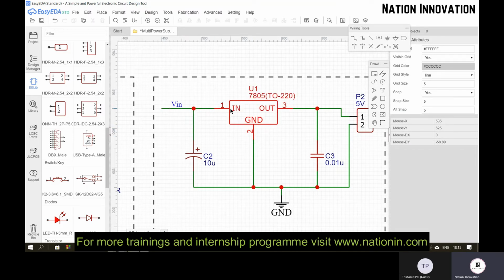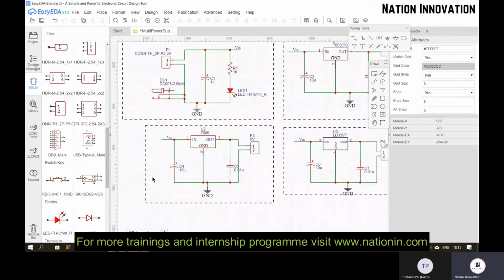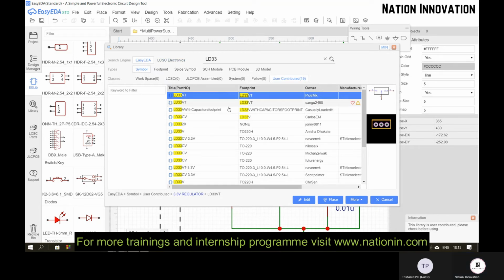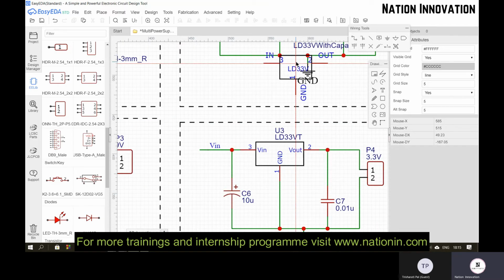The input will be connected to the input of this 7805, and output will be taken from this output pin, and the ground will be connected with the ground flag. I guess the naming of the pins is wrong here. Let me check. So it is correct. The third pin is the input, the first pin is ground, and the second pin is output here. So it has different pin names.